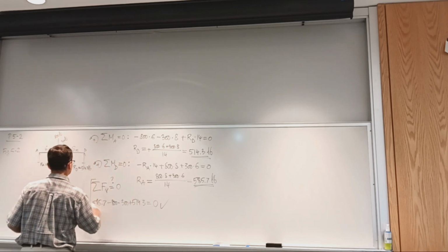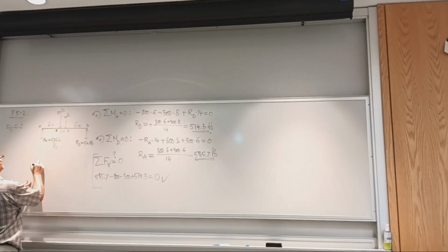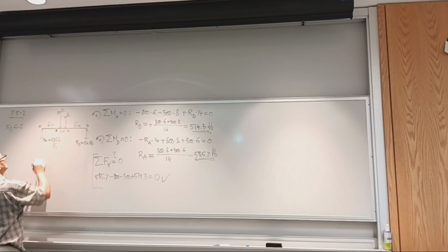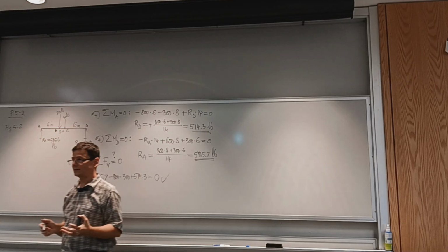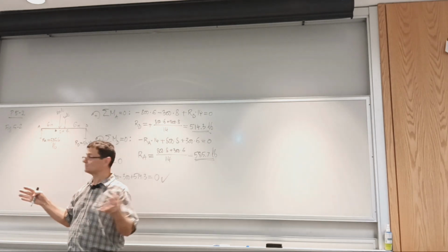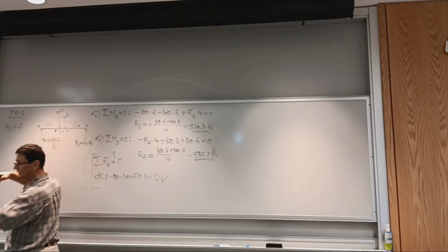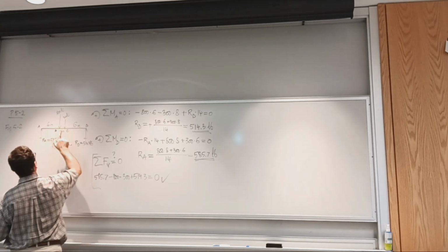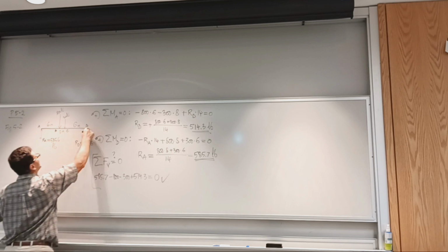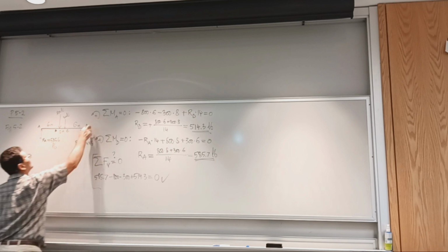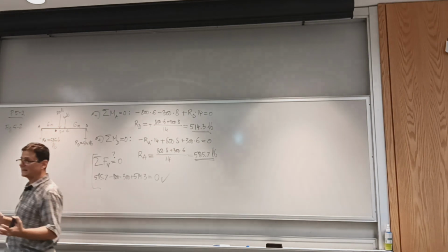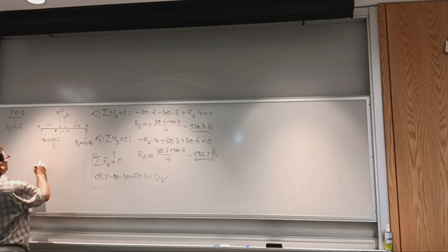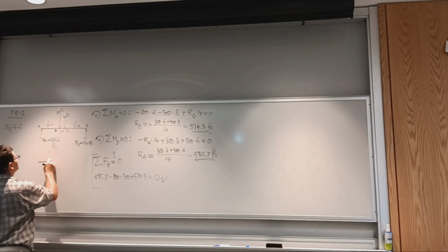Okay, so I need the space to draw the diagrams. This can go above and below. It should go above and below. The moment diagram is going to be all positive. I told you if the beam smiles, if it looks like it's smiling, I'm talking deformation, it means the moments will all be positive. But with a force coming from below, it may not. Or if I have an overhang and a force down, that will be the case. But smiling beams are not always apparent. Humor is of different types. There are black humor and silly humor.